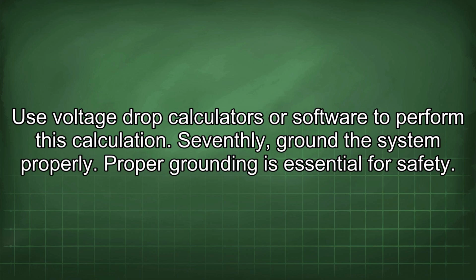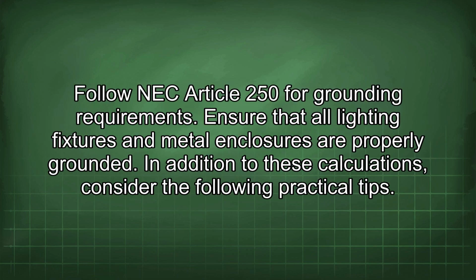Seventhly, ground the system properly. Proper grounding is essential for safety. Follow NEC Article 250 for grounding requirements. Ensure that all lighting fixtures and metal enclosures are properly grounded.